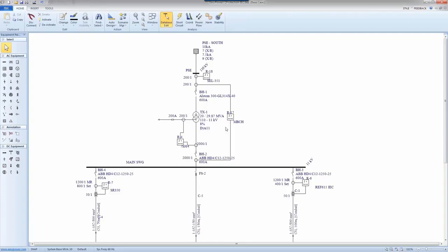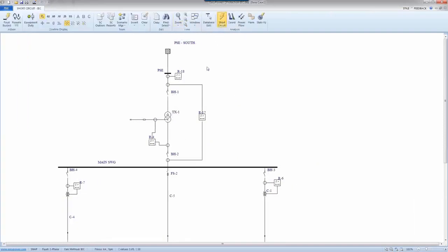That being said, you look at this file, which is new. I talked about different currents, so I switched to short circuit, and you would see the initial. You would notice the terminology that has changed here. 1, 2, 3, 4 type of breakings that have been added here, and a steady state. So this one becomes 20 millisecond, 50 millisecond, 100 millisecond, 250 millisecond, and a steady state. You would imagine, and it makes sense, that these are the breaking currents. So this is the initial.